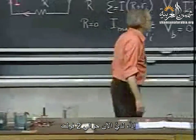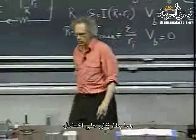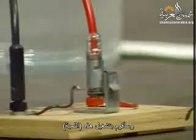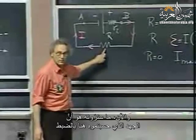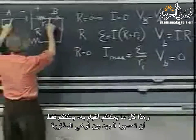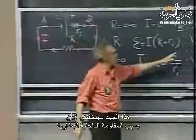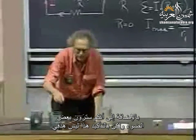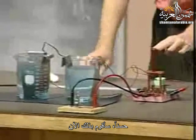Now what I will do, so I have now about 2 volts between these 2 plates, 2 batteries in series. I now have a little light bulb here, and I'm going to turn on the light bulb. And now what you will see is that the voltage that you measure right here, that's all you can do. You can only measure the voltage at the plates of the battery. That now this voltage will drop because of the internal resistance of the battery. In addition, you will see some light, but that's really not my objective. For those of you who are sitting close, you can see this light bulb is going to be lit. So I do this now.